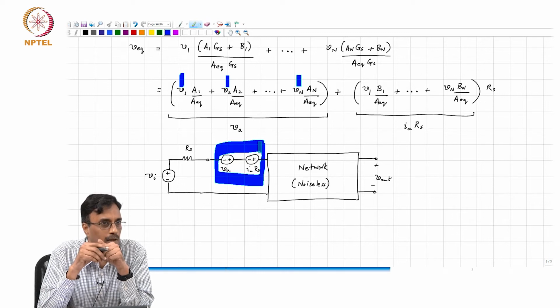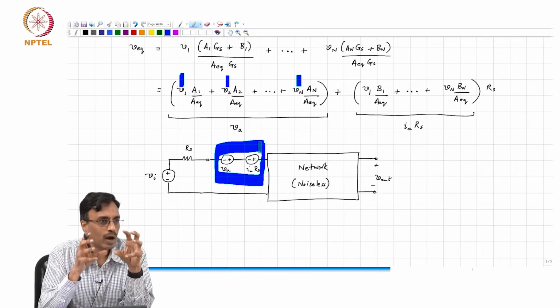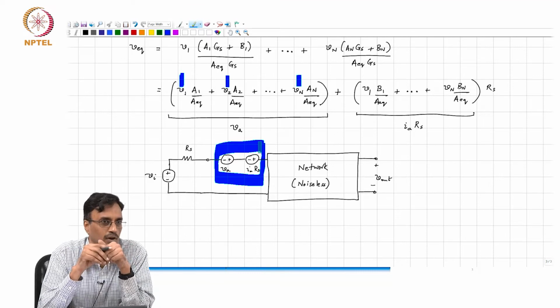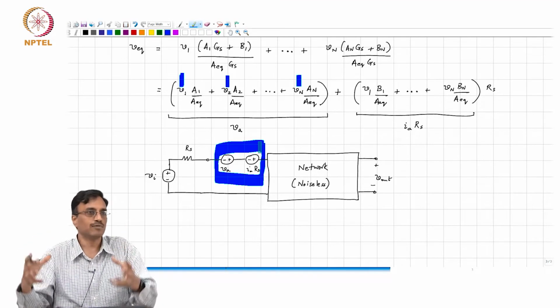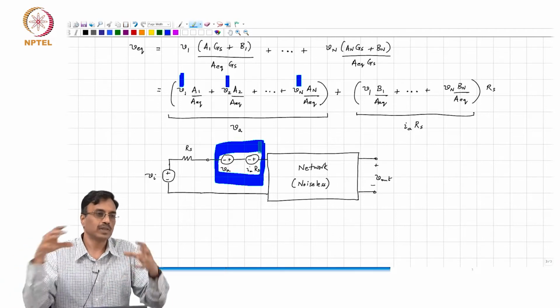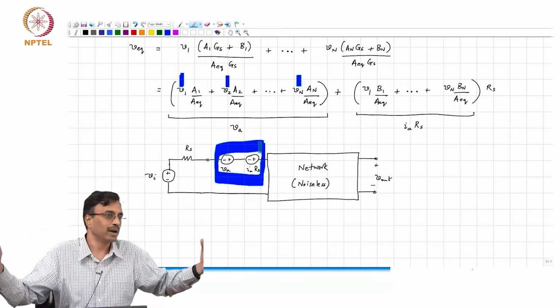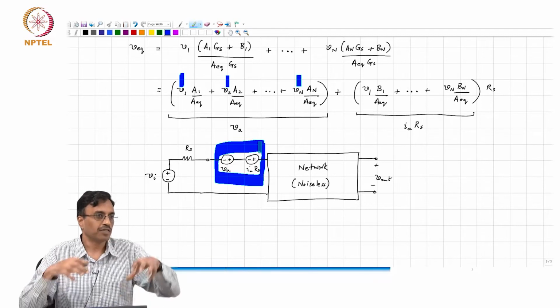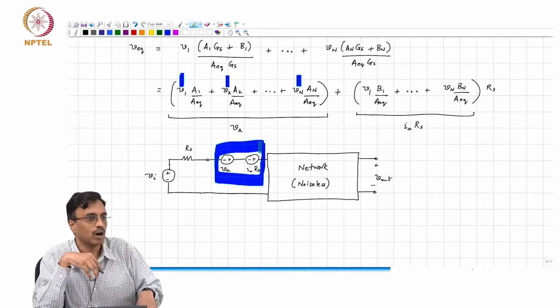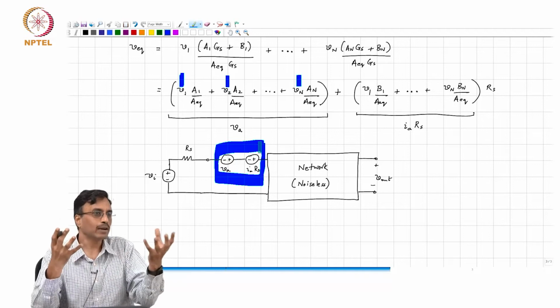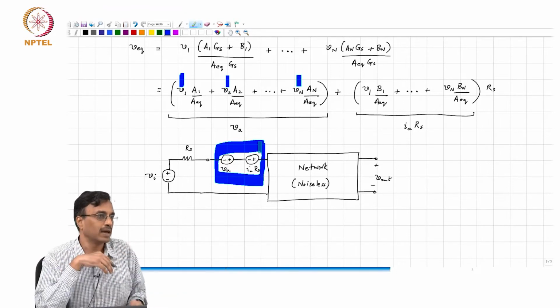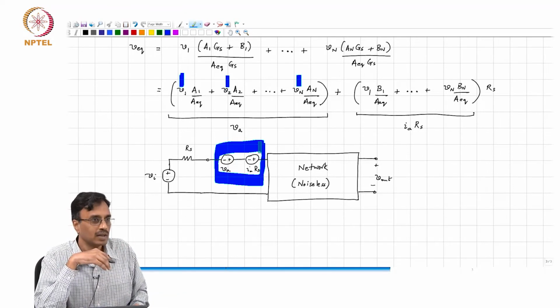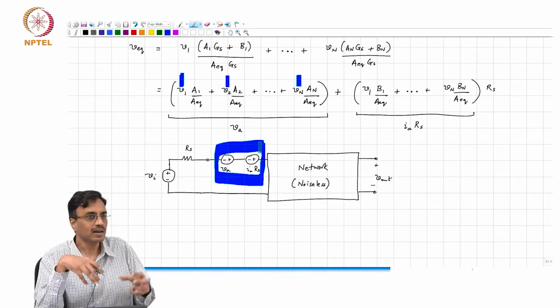That is the reason why we started off this input referred noise discussion, so that you, the user, can take this information and put that in your, presumably, bigger system. You want to see how the noise of my block impacts your system. So, what you would like to do is take the model of my 2-port, including noise, and plop it inside a bigger model.